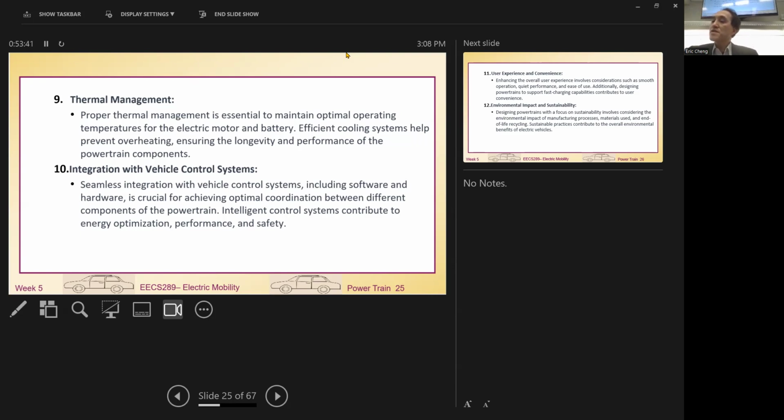They may use this field bit for information, this field bit for control, what kind of frequency, what kind of pulses. They are all different from different manufacturers. So there isn't any international standard yet. It all depends on your own company, how to use the CAN, how to program your own prototype. That means one company's motor cannot be used for another company's vehicle because they are not compatible. The motor itself may be the same, but when they program it with the CAN, they become different. So how to be compatible, how to work with the VCU is also quite different.